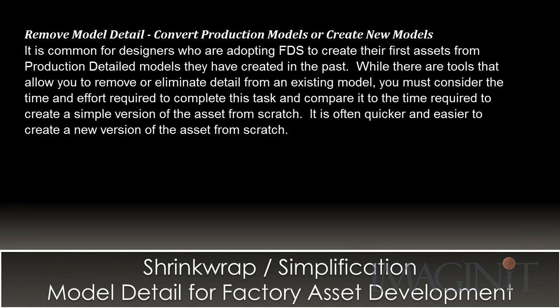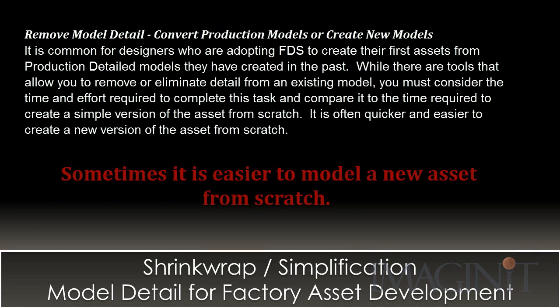It is common for designers who are adopting Factory Design Suite to create their first assets from production detailed models they've created in the past. While there are tools that allow you to remove or eliminate detail from an existing model, you must consider the time and effort required to complete this task and compare it to the time required to create a simple version of the asset from scratch. It is often quicker and easier to create a new version of the asset from scratch.